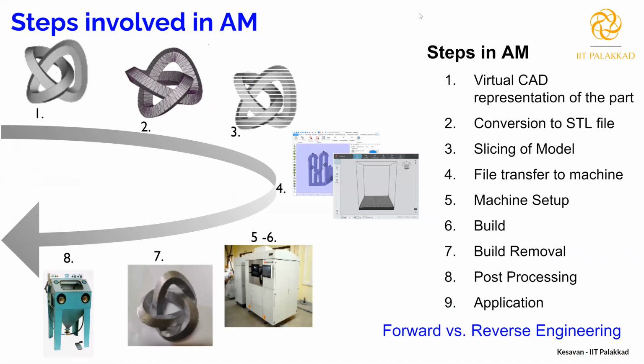There is one question from Prithvi Rajan. He asked, if you need to print tensile coupons along the X and Y axis, is it possible to print without warping? What has to be done to mitigate residual stress in such a case where reorientation is not possible? First, you can print. For tensile coupons it is not a problem, right? The length will not exceed something like 100 or 120 mm. So 100 or 120 mm you can easily print in all three directions. So that's not a problem. Even we are printing tensile coupons in all three directions.